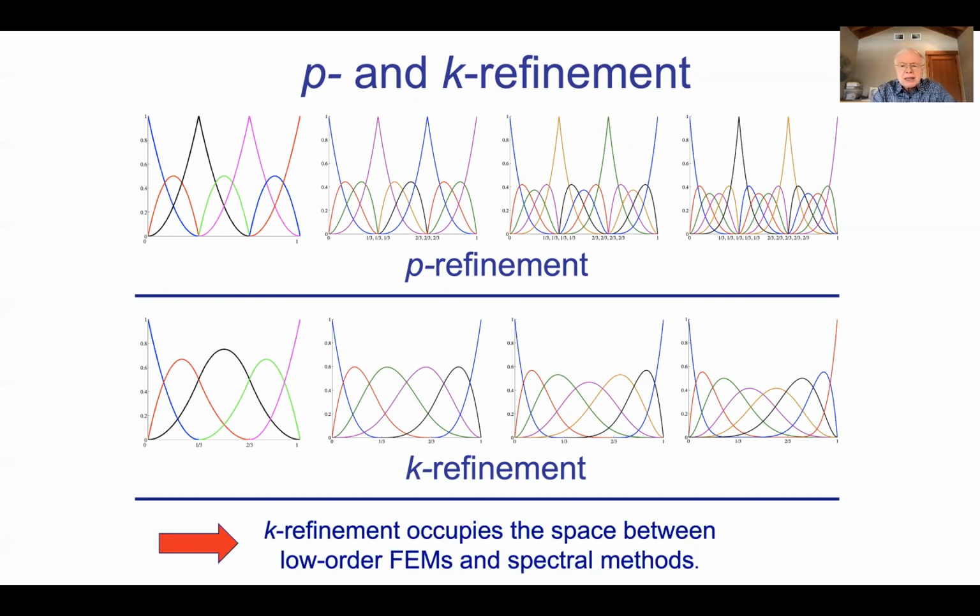Now, what this technology gives for you is something that we never had in finite element analysis. Namely, we never had geometrically adaptable functions that were smooth with essentially any order of smoothness we were interested in. We had C0 finite elements, we had discontinuous finite elements, and a few and far between C1 finite elements.